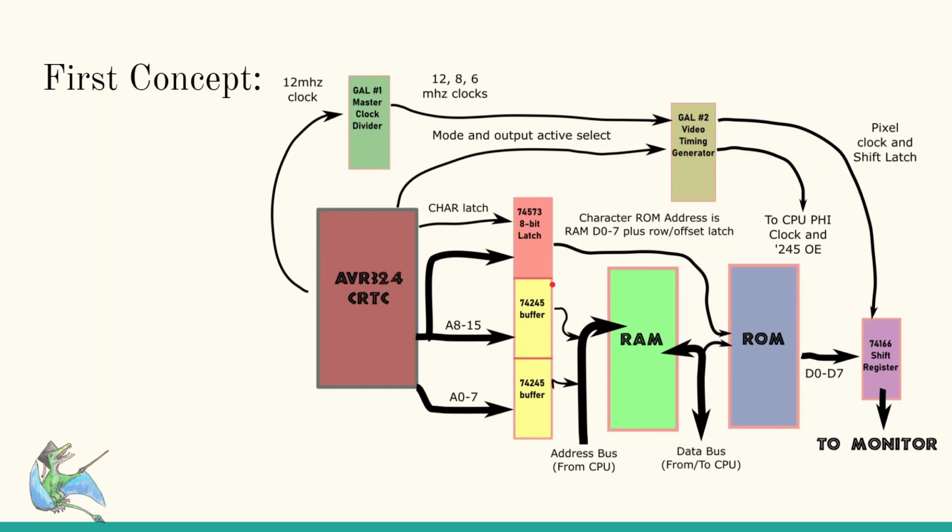It also has an output enable, which is mentioned over here. On command, you can switch between it driving what's coming out this side, or going to that tri-state mode where it no longer drives a bus.